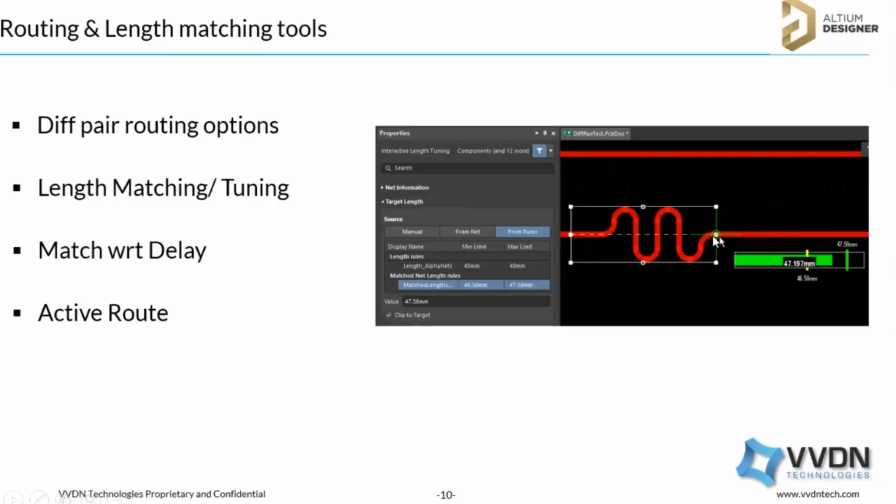Once you reach that, in Altium there is a good advantage. Once it has reached the target, it will highlight in this green color, on the right side you are seeing there: Maximum reached. As per the rule, we have reached the maximum length. So after that, it will not allow you to increase. So by mistake, you don't need to manually adjust and verify. So that will be easy for us.